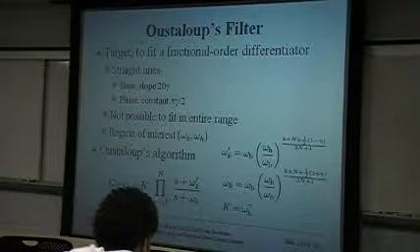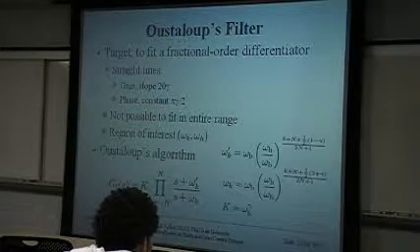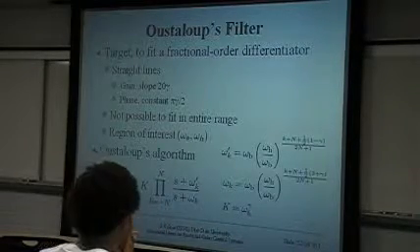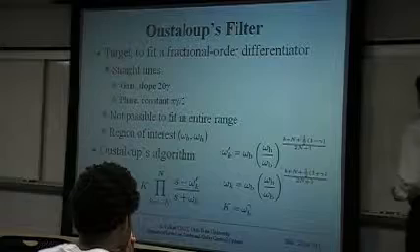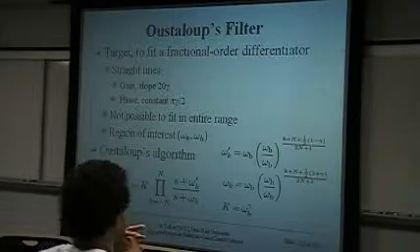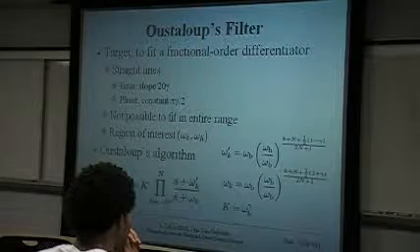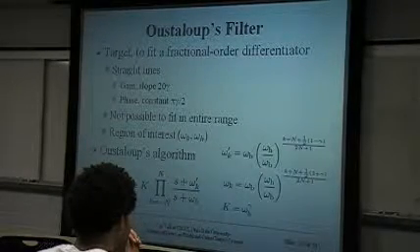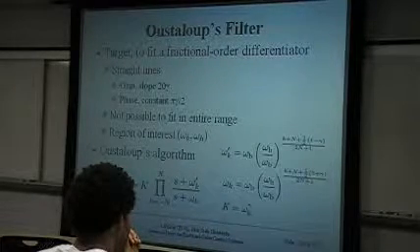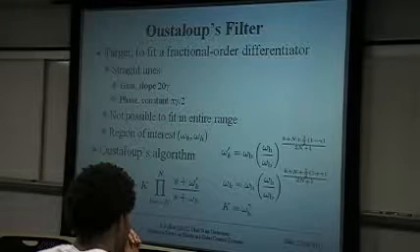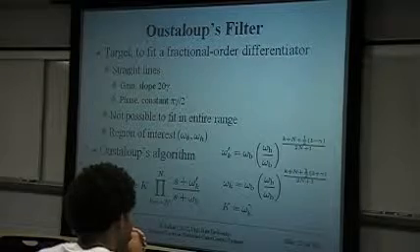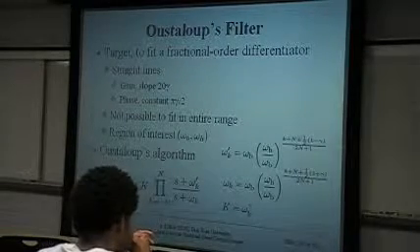So now the question is how we can approximate a fractional order differentiator. Before that, for fractional order differentiators such as s to the power of 0.2, we know that the Bode diagram for it is a straight line with a slope of 20 times 0.2. Or if this one is gamma, then it should be 20 gamma.